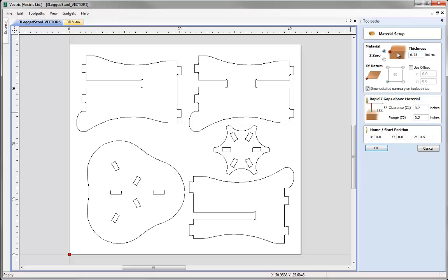At the moment it's set to the top of the block, but if you're cutting parts out like we are here, it can be beneficial to set it to the bottom of the block. So if I click that option here, you can see that'll change. It's indicating Z0 on the bottom of the block, or another way to think of that is Z0 is now on the top surface of the table of your machine or your sacrifice sheet. That means that when we do the cutout and it sends the tool to Z0, then it should be very precise in going to that depth rather than referencing that depth from the top of the material where we may have a difference in material thickness across the part which will add inaccuracies in. So here I'm happy with that.